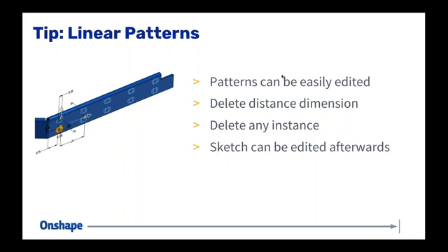Another one that commonly comes up is, can I dimension my patterns different ways? So by default, when I create a sketch pattern, for instance, it has default distances between values, right? So if I'm patterning a hole, a circle, let's say, I'm giving it X distance between each instance of the pattern, which is just a kind of a dumb number, so to speak, right? It's just X distance between each hole. But what if I wanted 6 instances between this and the end of the part?